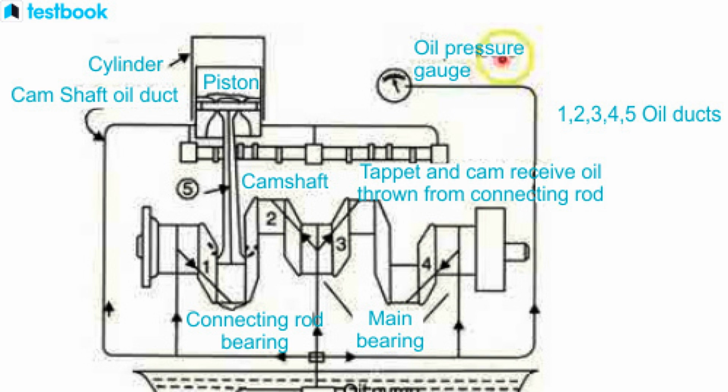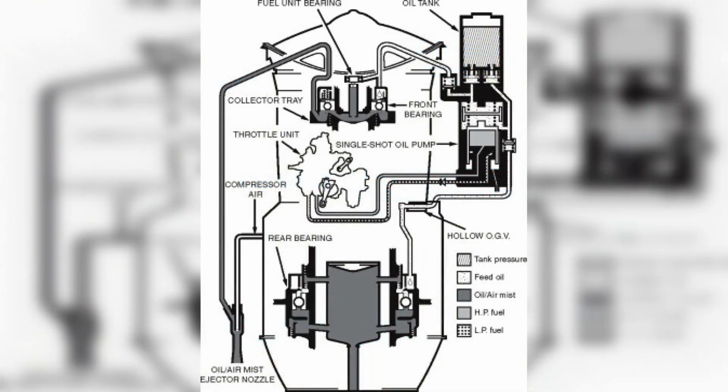Typical composition of a lubrication system with dry crankcase: oil centrifuge, cooling radiator, full flow oil filter, bypass valve, coil used for heating, oil tank, pre-start oil pump, oil intake strainer, main oil pump. When the ignition is switched on, the pre-start oil pump starts working, pumping the oil from a separately located self-contained tank into the main line, bypassing all oil filters.